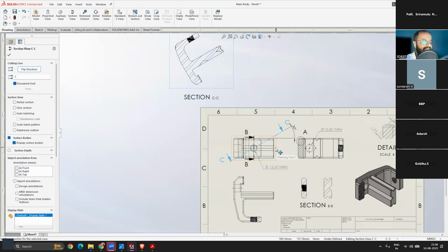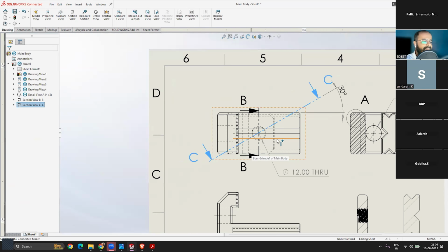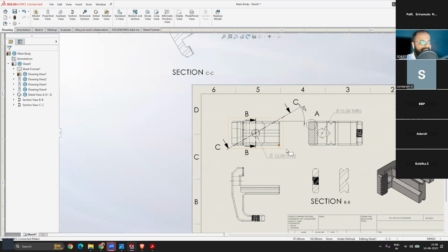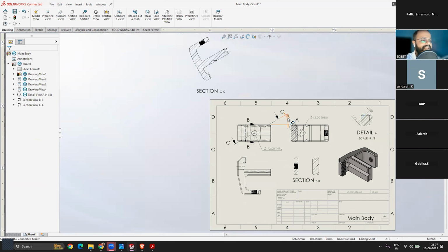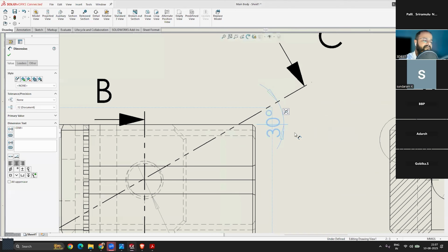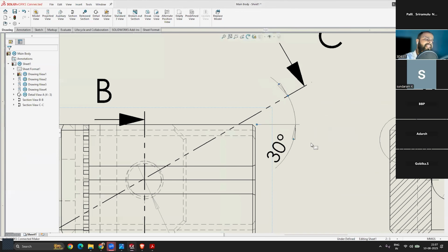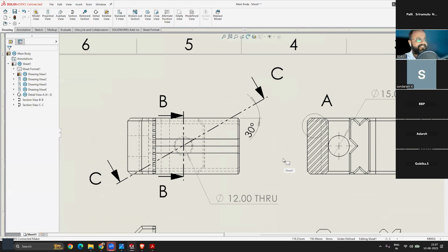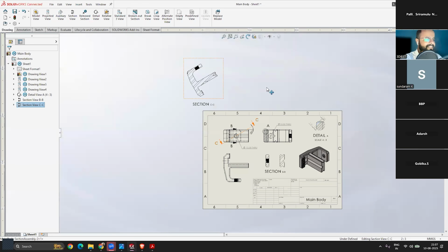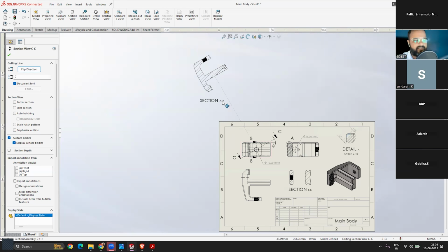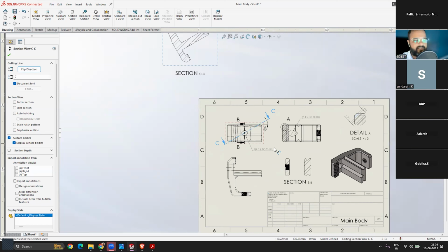Okay, sir. Okay, so I understand. Whatever lines or sketch you add, once you select that sketch and activate the section view, you will get details like that, right? So all the time we have complete freedom, at any angle, at any line, across any axis, we can get our sections. And again, section views are attached to the views, and it will always be perpendicular to the axis. So if you want to place it anywhere on the drawing, anyone just ask your questions about drawings, because drawing is one of the most important things.